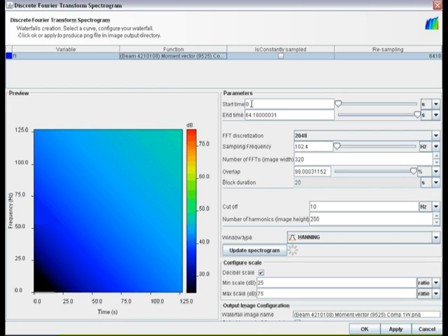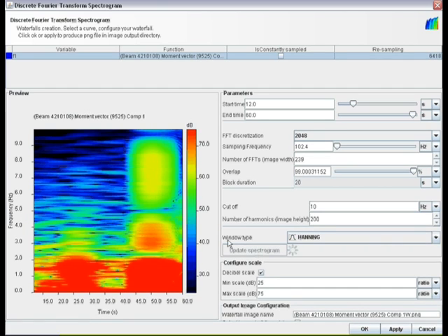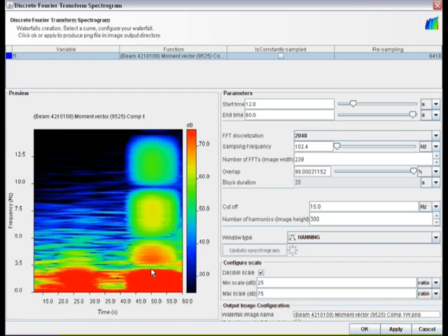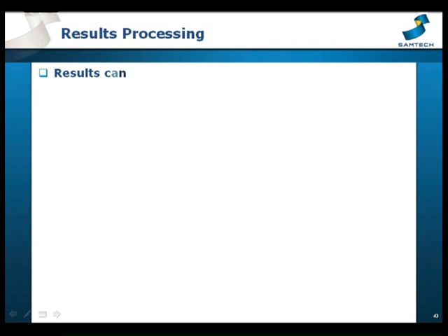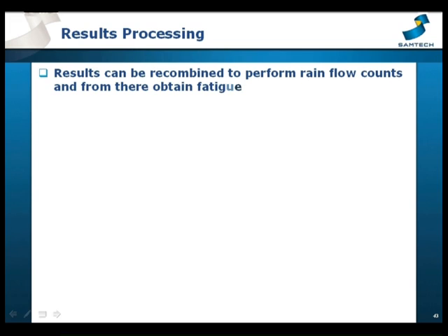These diagrams are basic FFT transformations performed in small time intervals. The color scale should correspond to the y-axis of the FFT transformation, while the y-axis of the waterfall corresponds to the frequency. The scaling and colors of the waterfall diagrams can easily be customized in the dialog box, as shown here. One can clearly see on the results that some higher frequencies were excited by the emergency stop and not by the wind itself.